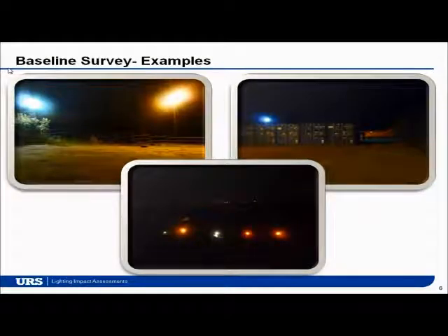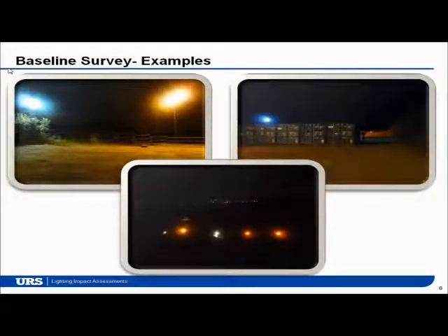It can also show how it's really good at informing us what's on the site already. In this instance, there was a lot of obtrusive lighting already on the site. There's very high masts with 3 or 4 floodlights on them, lighting an area that didn't need to be lit. It was storage containers that wasn't being used at night. And you can see the view from about 1/4 of a mile away, where it's very obtrusive and it's affecting the night sky.